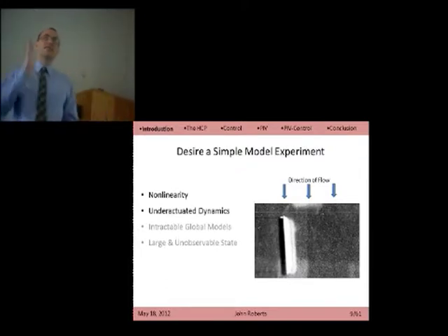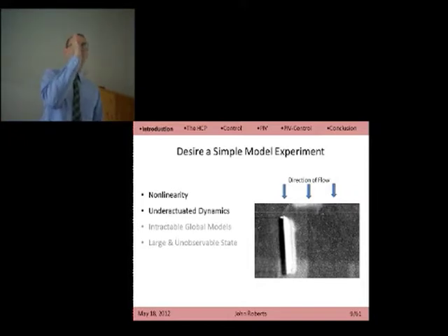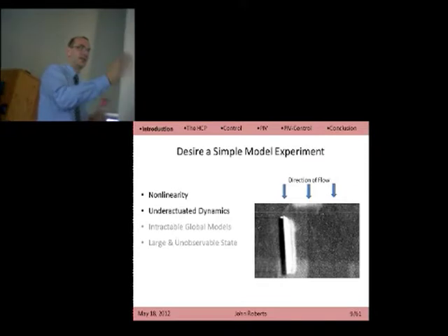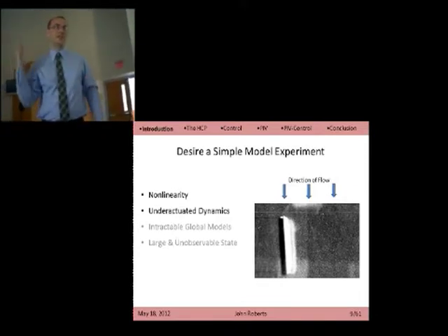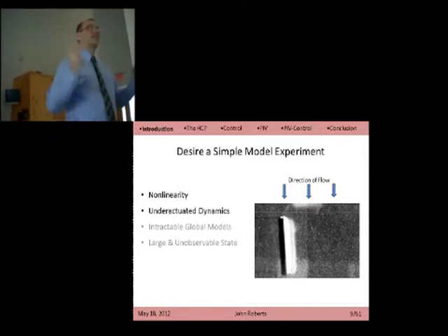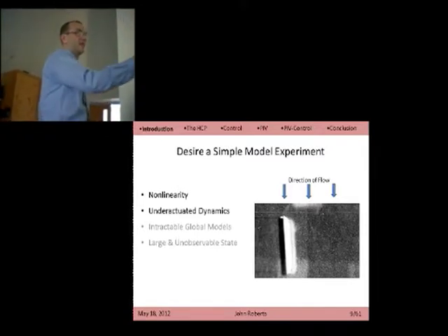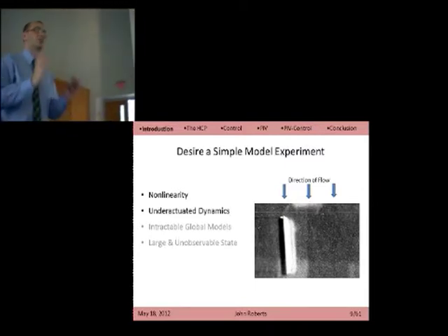So if you imagine, instead of balancing against gravity in the vertical plane, let's say you balance horizontally against a fluid flow. So you're like a weather vane. And the weather vane wants to point downstream because of weathercock stability. That's the stable configuration. But upstream, there's something like an unstable equilibrium pointing upstream, where a little perturbation will knock it and it will fall over. So we want that sort of geometry.